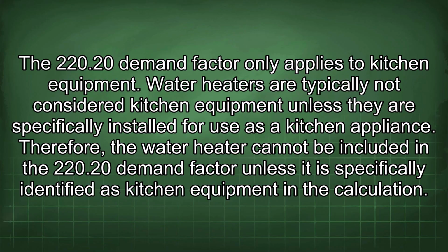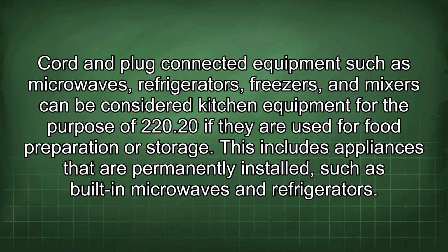220.20 demand factor only applies to kitchen equipment. Water heaters are typically not considered kitchen equipment unless they are specifically installed for use as a kitchen appliance. Therefore, the water heater cannot be included in the 220.20 demand factor unless it is specifically identified as kitchen equipment in the calculation. Cord and plug connected equipment such as microwaves, refrigerators, freezers, and mixers can be considered kitchen equipment